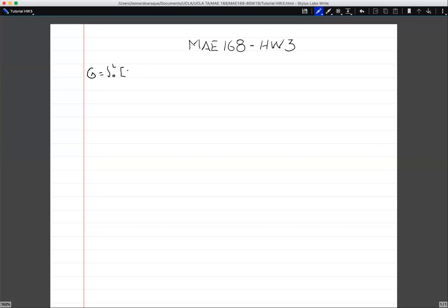And it should look like this form, where we have the conductivity term, the cross-section area for the fin, the derivatives of the function T and the weight function v prime, the perimeter, the convection term, T infinity accounts for the ambient temperature, room temperature, and the last term corresponds to the boundary conditions. I think I missed the K here.